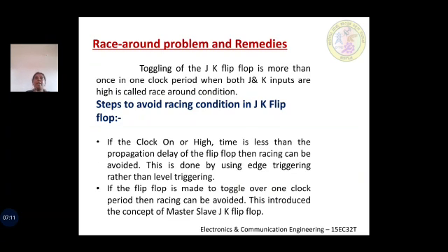The main use of asynchronous inputs is that they are totally independent of the synchronous inputs and clock, which means they can be used to set or reset the flip-flop at any time regardless of the conditions of the other inputs.